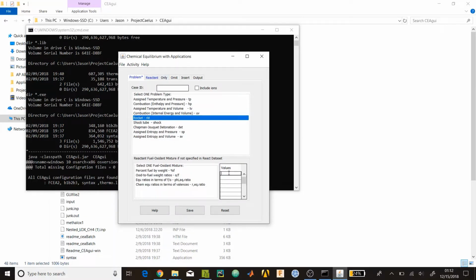ratios. If you're first researching the correct ratios, if you're trying to get stoichiometric values for oxidizer to fuel ratios, basically what stoichiometric means is it goes through complete combustion. Like all the products cancel out to make reactants. You won't have any leftover reactants. Basically all of the fuel and oxidizer are used up. So that's stoichiometric, but sometimes you actually don't want stoichiometric because it's too hot, to the point where it literally just melts your chamber.